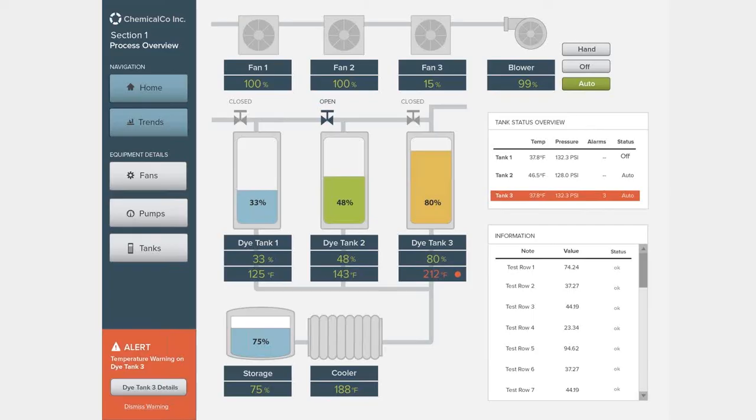So here's our final screen. We've used color to tone down some of the non-critical data elements. We've reserved red for alarm states, but we've made sure to pair it with secondary indicators. And we've made the foreground element stand out more by toning down the background and making it grayer and more neutral.